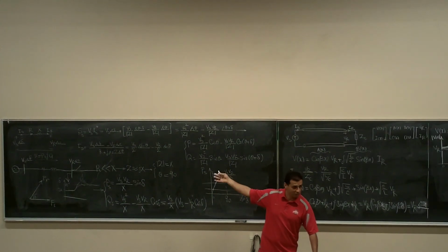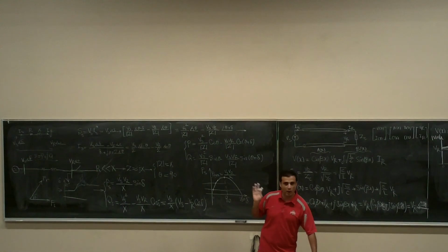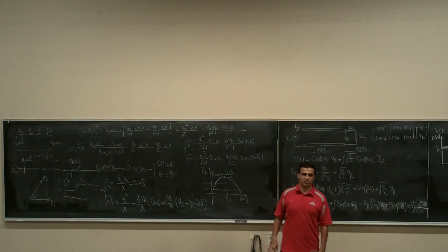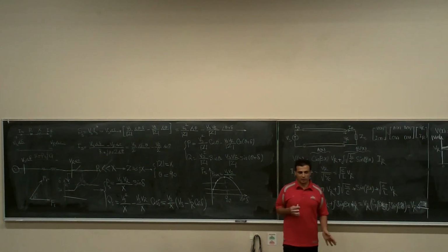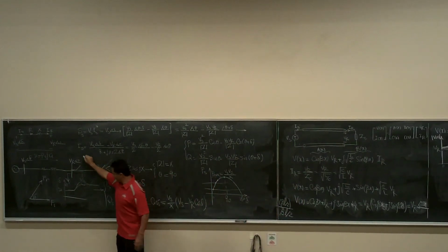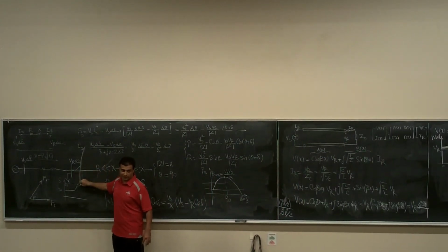I have all this power here, and I cannot generate anymore. You know what I'm saying? Right now, the rule is as soon as the grid is gone, you have to shut down. You are not allowed to generate any power. But they are changing the rules, and they are coming with a smarter system. So even if the grid is gone, you should be disconnected from the grid. You should make sure you are disconnected. What's the problem if you are not disconnected?